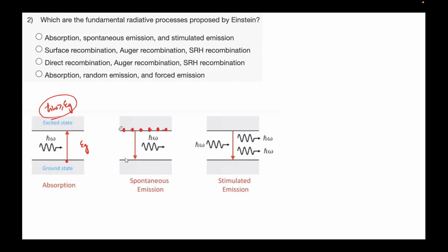Now what can happen is, and this is the excited state for the electron, if there is a hole available here, this electron can drop down to this hole and we'll have an electron-hole recombination. Here it was electron-hole generation, here it's a recombination process, and in the process of recombining, again this h cut omega will be equal to Eg. Again, please note that I'm not considering any states which are above Ec or below Ev. That's an assumption that I'm making.